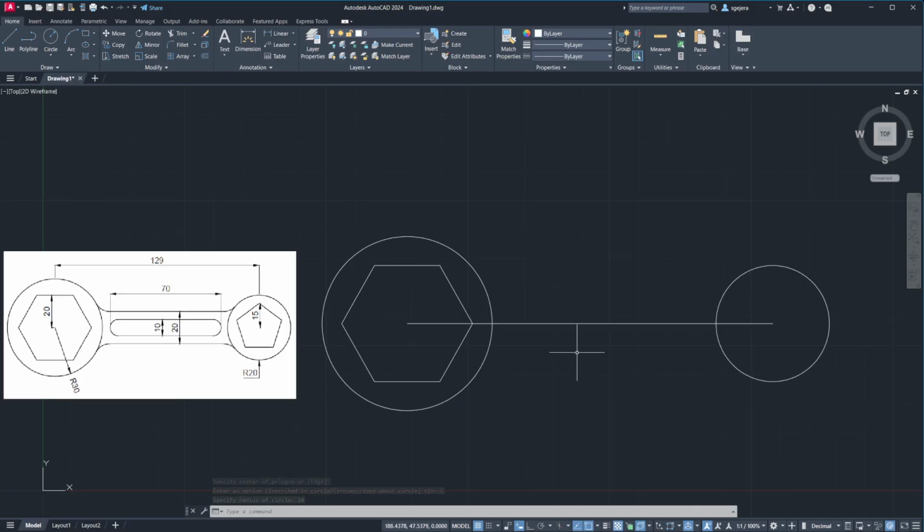Okay? Sir, what is the shortcut for the different options, whether inscribe or circumscribe? Oh, I know that's possible. So, let's try. I think it's just the starting letter. So, for example, this. Then, let's do it over there. If I press I, there. You just press the letter. So, C or I. I is for inscribe. Notice that the dot pointer changes. So, if it's I, it's inscribe. If you do C, then it's circumscribe. So, that's a shortcut.